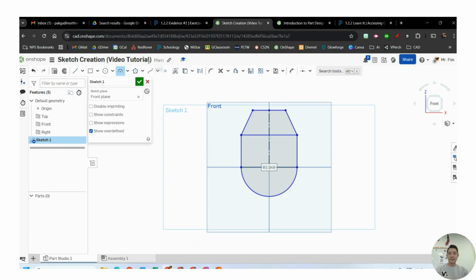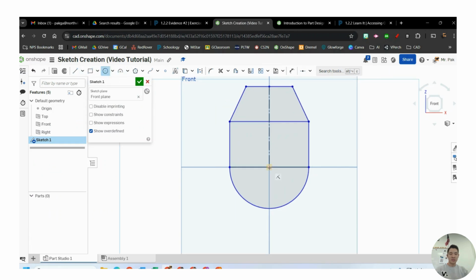All right. So I'm going to find circle, make sure it's on the origin. Notice that the dot turned to a square around it. That means I'm locked in. I'm going to generally make the circle. We'll add dimensions to it later. And then it said I wanted this to be a construction line.